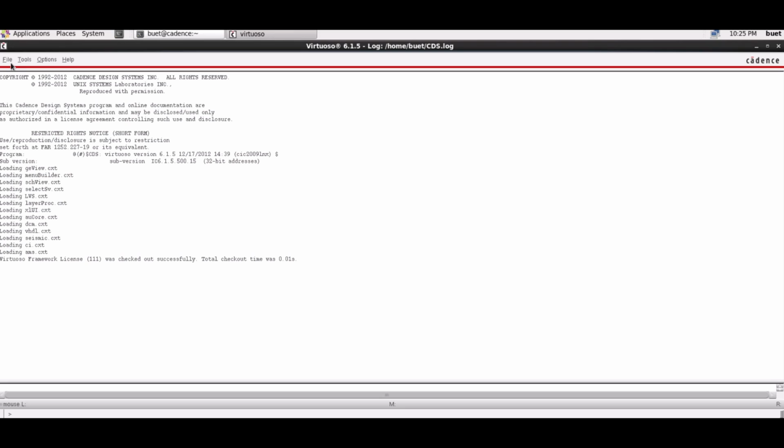Now, how to create your library and attach it to the existing technology. Now, all the entities in Cadence are managed using libraries, and each library contains cells. Each cell contains different design views, containing subdirectories, each one containing files. Thus, for instance, a certain circuit, for example, an inverter, can be stored in a library, and such library can contain different logic blocks stored as cells. Each block contains different views.